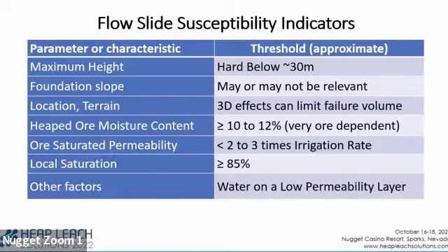What this means is that you don't typically get penetrations of the failure zone below about 30 meters, because the confining stress starts to be enough to hold it up. So I generally limit my investigations to about 40 meters deep, because the liquefaction zone's not going to reach down deeper than that. Now you also have to pay attention, when you're on the slope of the heap, it's that 30 to 40 meters below the slope. So your heap can be 200 meters high and the bottom 30 meters of that slope can fail, can liquefy. So there are some implementation issues on that recommendation.